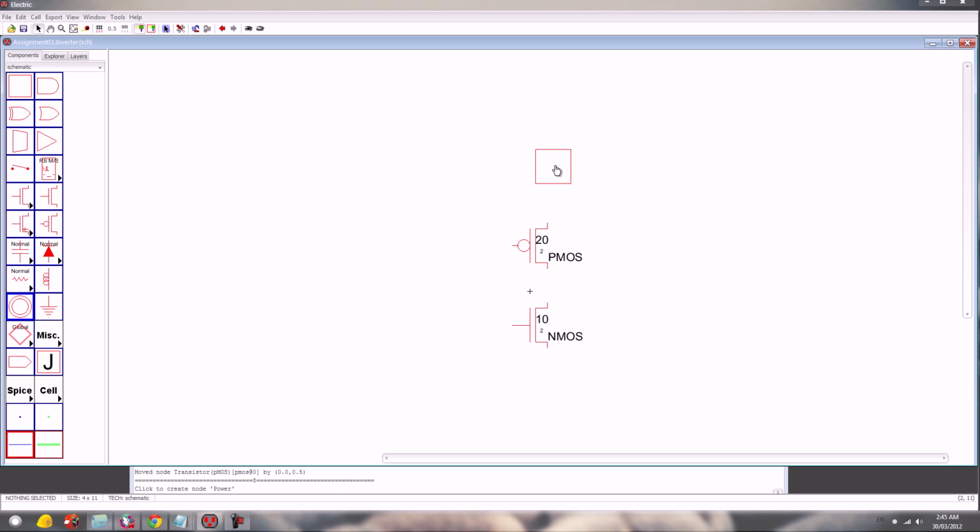Add in a power supply, the circuiting, and press Ctrl B to adjust the size to your liking, and put it there. Add in a ground, Ctrl B to adjust the size. And add in one output and input on the left and on the right side of the diagram.